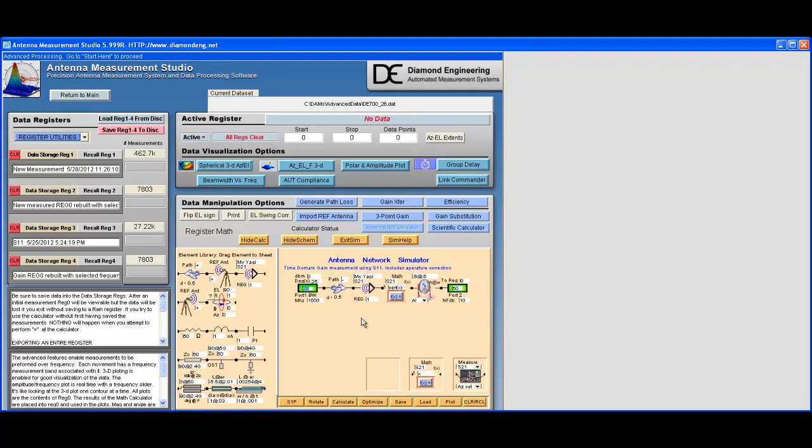In this schematic, we see a path, the measurement data, a math function, and a correction for the mirror. Because we're in S11 mode, we must divide the path attenuation by 2. That's equivalent to just removing the reverse path. So we have only one path to deal with.